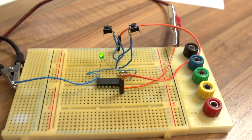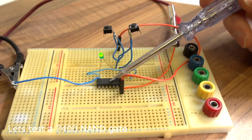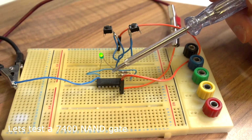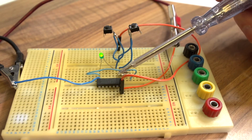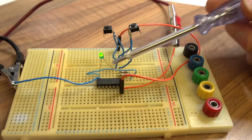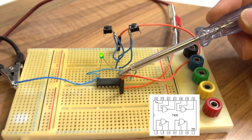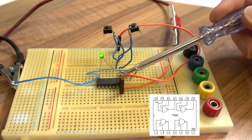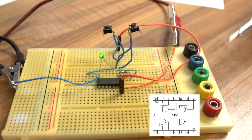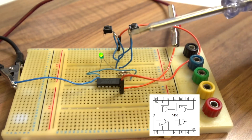And here we are with our first gate to try. Let me just explain what's going on here. We've got the chip in the board here, and this particular chip is a 7400 quad 2-input NAND gate, and I'll show the pin out for that on the screen here, so you can look at the designation of all of the pins of that chip. Basically, it's got 4 NAND gates in it, each with 2 inputs. And what I've done is supplied it with a 5-volt supply coming through these blue and orange cables here. So we're driving it with 5 volts from the power supply.